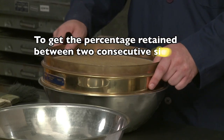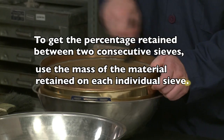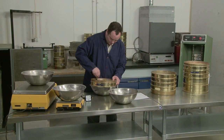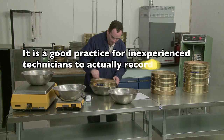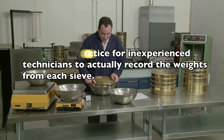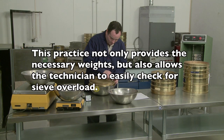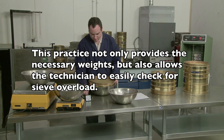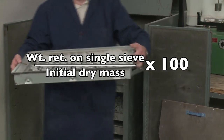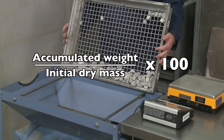To get the percentage retained between two consecutive sieves, you will use the mass of the material retained on each individual sieve. When this data is required, it is a good practice for inexperienced technicians to actually record the weights from each sieve. This practice not only provides the necessary weights, but also allows the technician to easily check for sieve overload. Use the percentage retained formula, only substitute the accumulated weight for the weight retained on a single sieve.